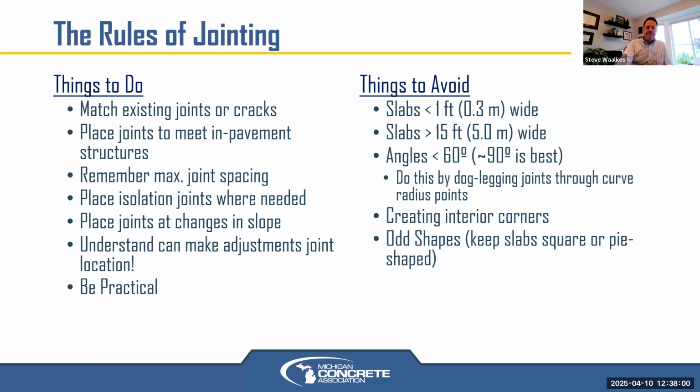Gotcha. Then there's another question of, would it be appropriate to add a joint on or before culverts? I will tell you this, I've seen a lot of drive approaches, whether it's commercial, but in a ditch situation where there's a culvert going underneath the drive, depending on the amount of aggregate base material in between the bottom of the slab and that culvert, and the culvert type, plastic, metal, or concrete, in general, I'd say yes, especially in those rural situations.